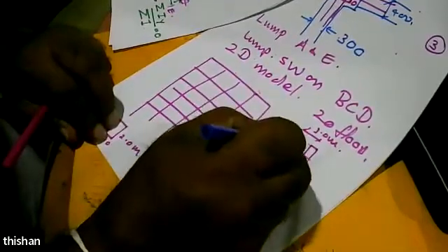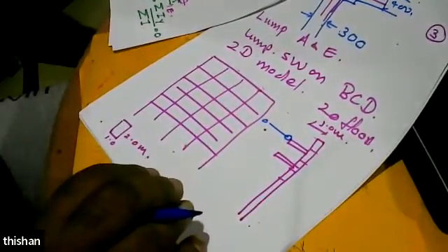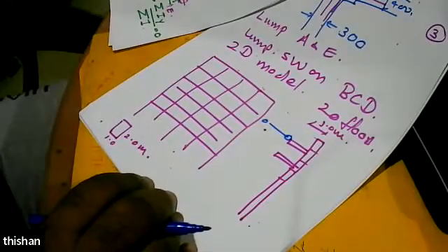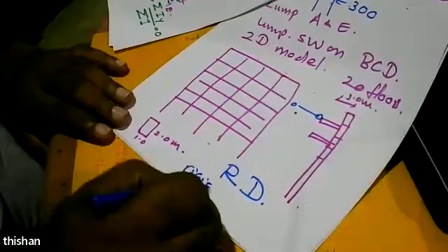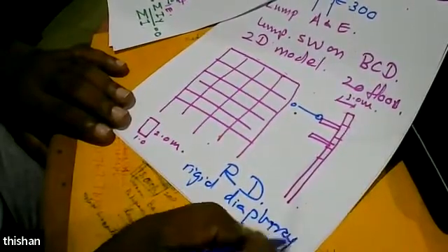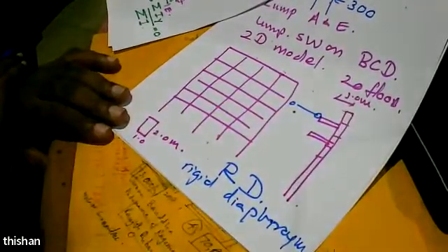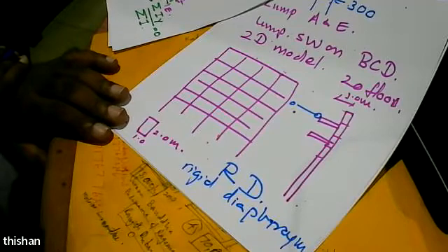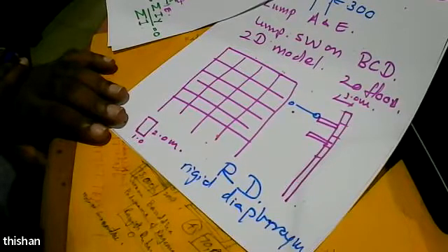And then we connect it like this, representing that on the floor, you can't have different deformations because a floor does not deform in its own plane, which means the floor must act as a rigid diaphragm. So you have to have something called a rigid diaphragm. The rigid diaphragm is represented by saying that the deflection at any point on this plane in a given direction is the same because the structure is non-twisting. The structure is balanced, it's not twisting.